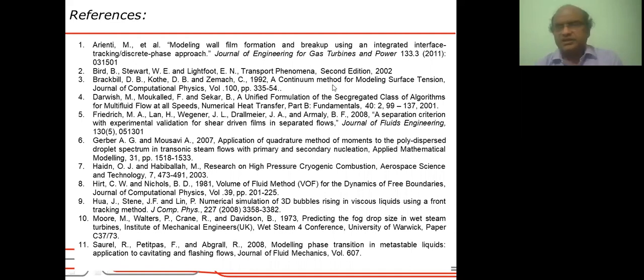Then there is something called thermophoresis. Thermophoresis is the movement of a discrete particle due to a temperature gradient. For example, if you look at a particle in a thermal boundary layer, there is temperature variation. So this particle will experience higher temperature on one side and lower temperature on the other side. As we know, temperature is a measure of the thermal velocity, the kinetic energy of air molecules. So on the side where the temperature is higher, the air will be exerting more momentum, and on the other side, less. So this particle will move in the direction of decreasing temperature.